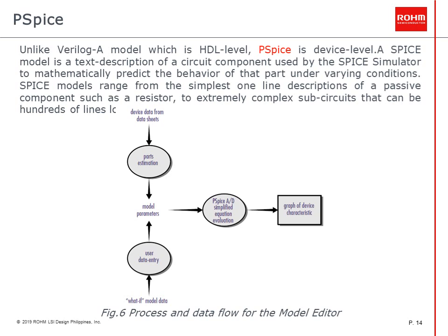After you prepare a design for simulation, OrCAD Capture generates a circuit file set. The circuit file set, containing the circuit netlist and analysis commands, is read by PSpice for simulation. PSpice formulates these into meaningful graphical plots, which you can mark for display directly from your schematic page using markers. Shown in Figure 6 is the process and data flow for the model editor.